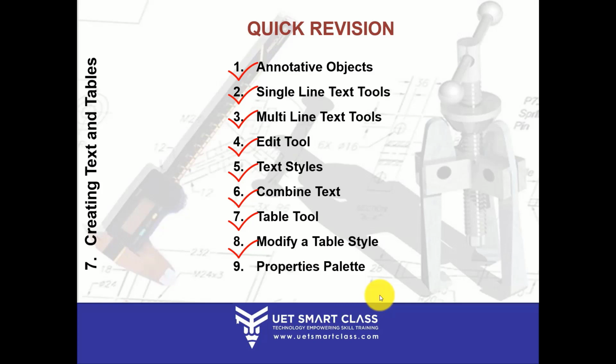You can even link your cell data with your Excel sheet so that you can update the Excel sheet whenever you want and it will be updated in your AutoCAD table as well, or otherwise you can update in your AutoCAD and that will be updated in your Excel as well, through download source or upload source.